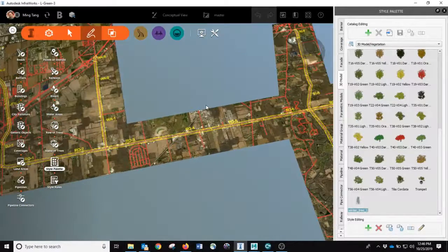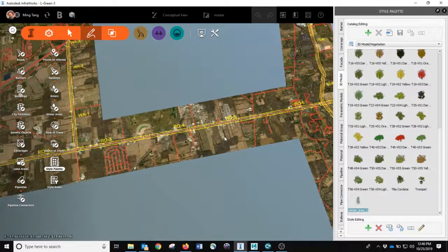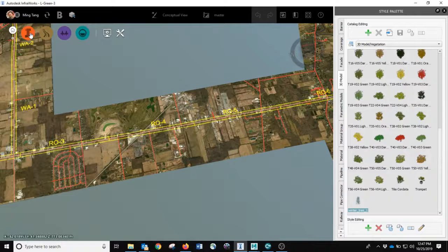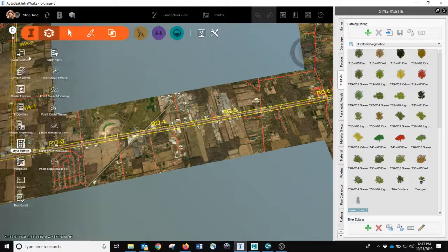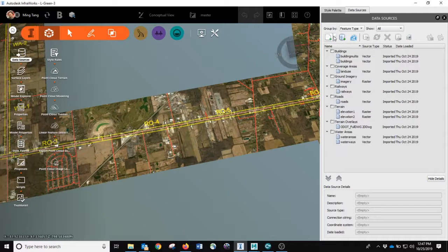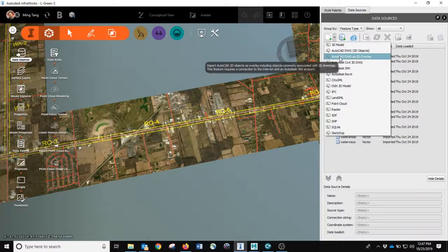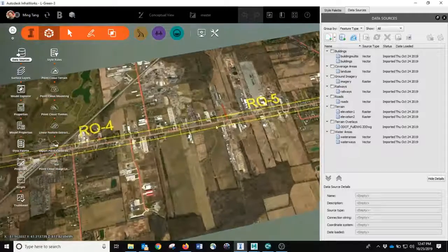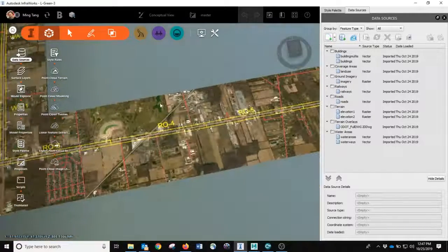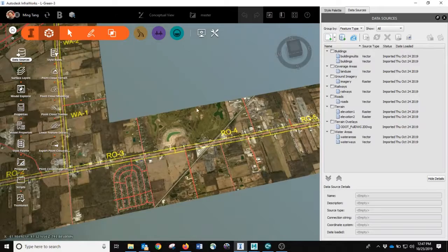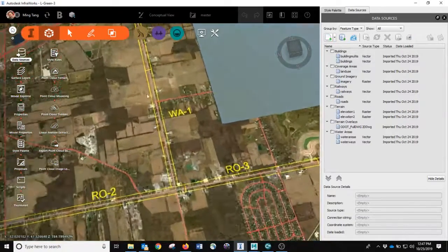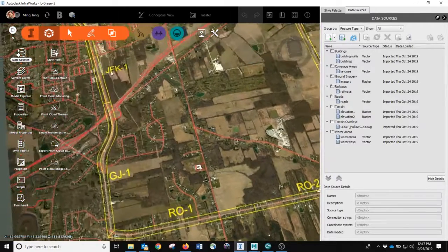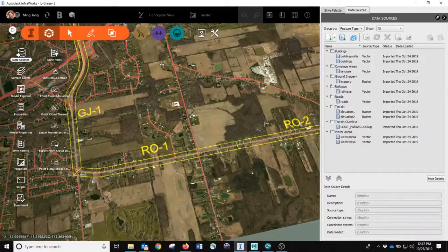So the first thing I will do is we have the overlay from the DWG file, which I can show you quickly. I loaded this through the data source, and I added a new data source as 2D overlay, which is AutoCAD DWG, and that overlay carries this line work. So once I add it in, I can scale it up to match our satellite image. So this gives you the reference about the site. Some of you are doing an RO1, some of you do the GFK, so you can see the site you're going to focus on.